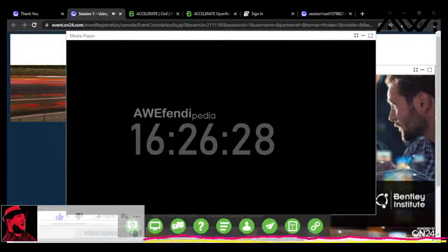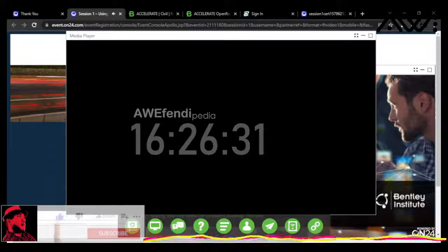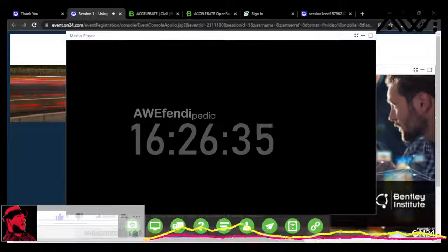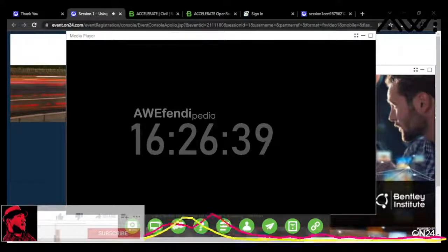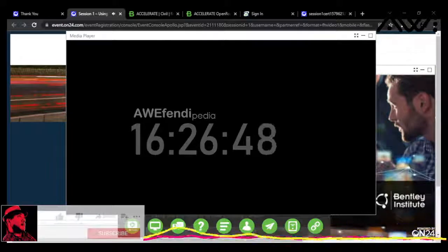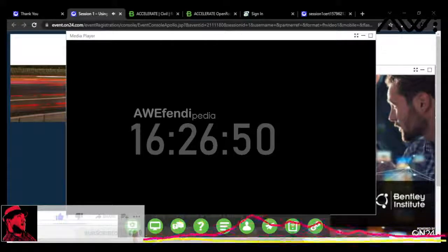Point list features allow me to not be so concerned with the order in which the shots were shot in the field book, but I can just reorder all these strings how I want them. Let's just show one more thing. If I highlight that point, I can move it up and down in its location in the string.